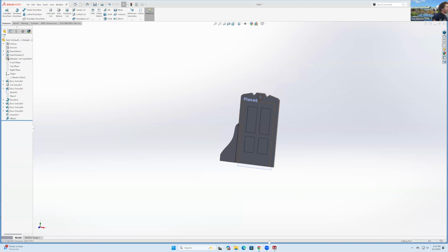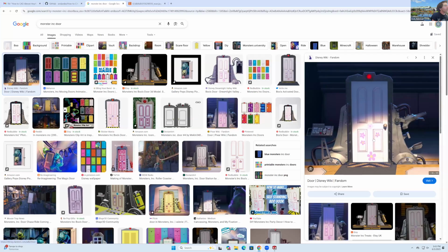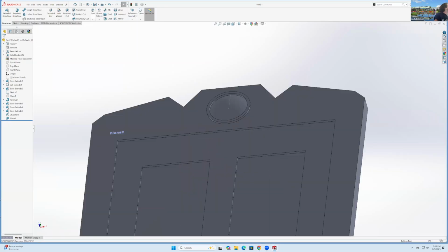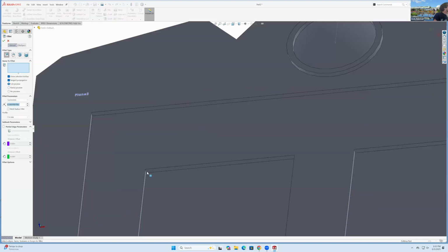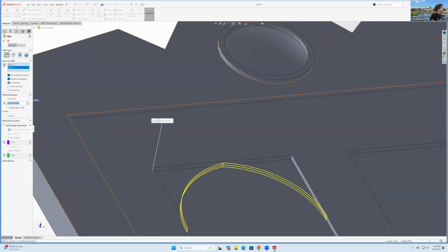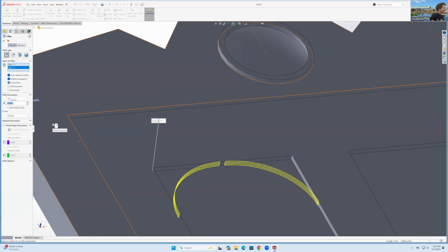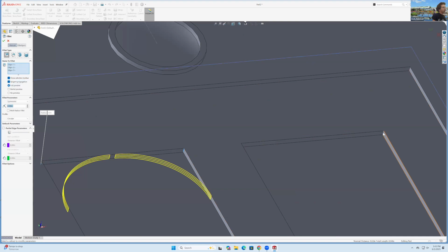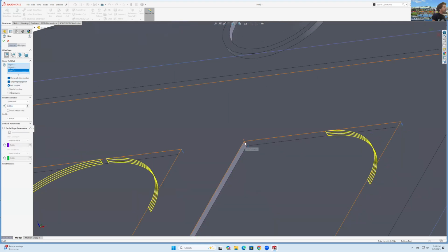And before we start doing anything, I'm gonna add a couple of details to the door. So for instance, well, it's not gonna look identical, right? But we can go here to fillet, choose those corners right there, maybe make that smaller to, let's say 0.3. Just like that.